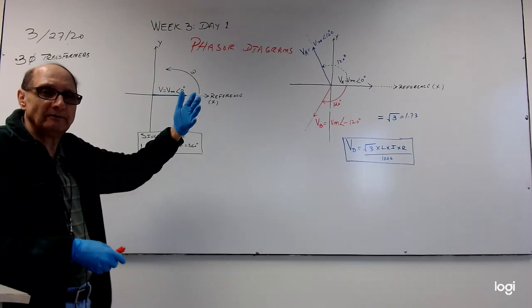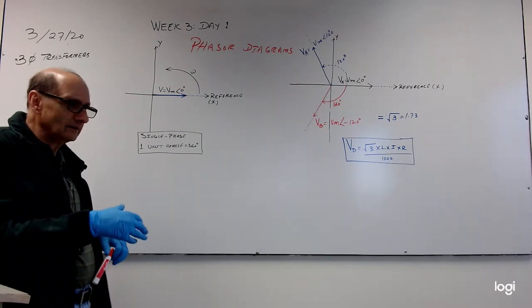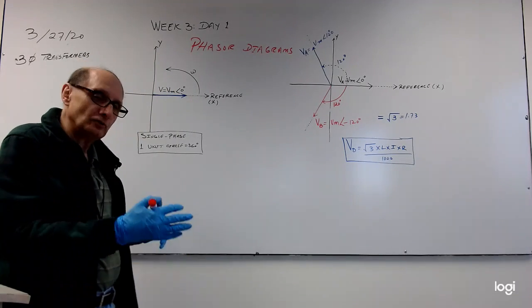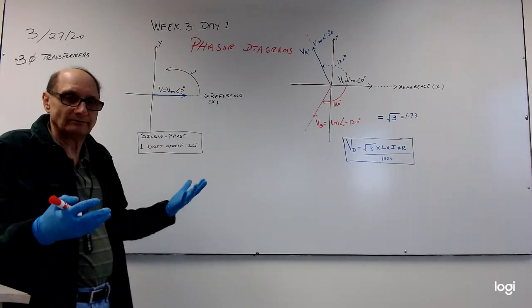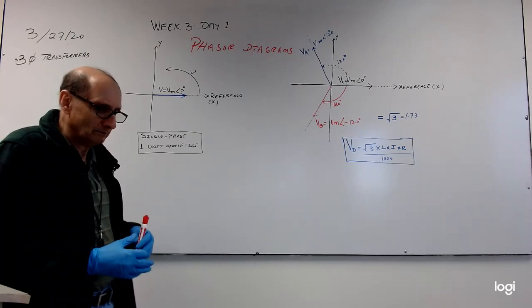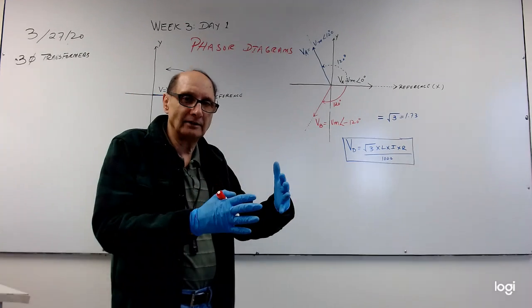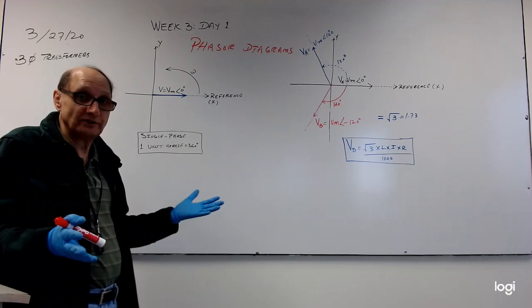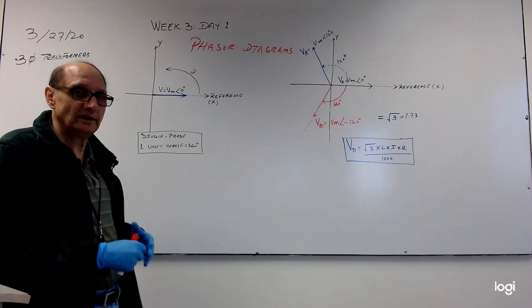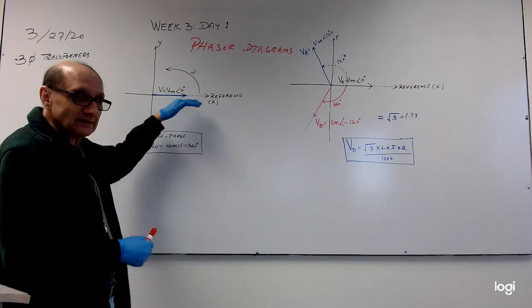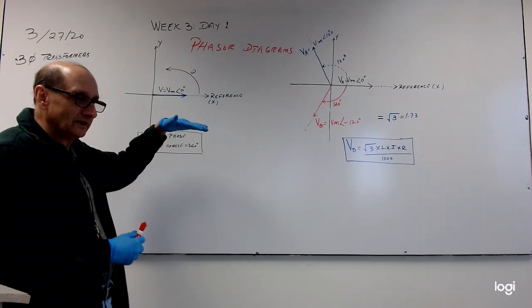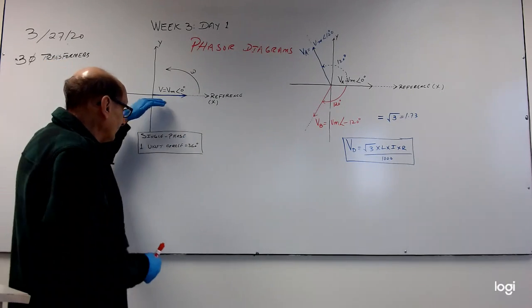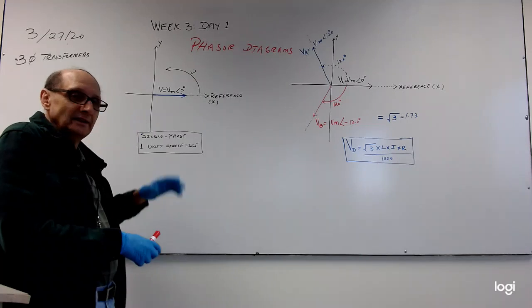But most of the time when it comes to single phase, whether it's a phase A or phase B, we do not actually show an angle. In reality there is an angle, but as far as single phase is concerned, there is no phase shift, so that's why we don't really show anything. This is just a brief review that when it comes to single phase, we have two wires, because definitely we have a hot and we have to go back, and that's the return path.